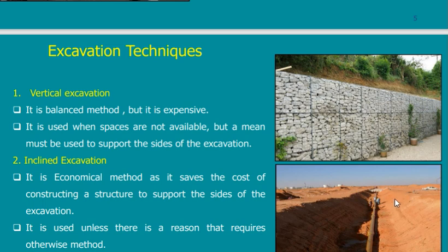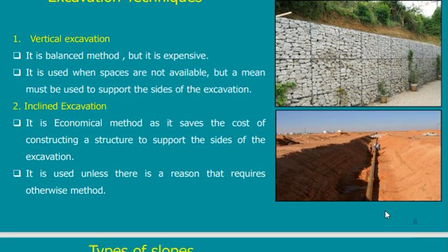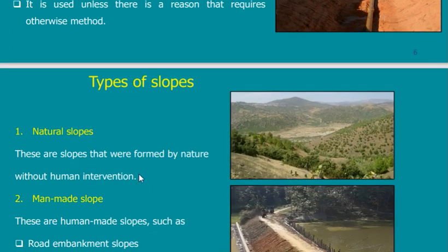In the case of this project in the desert, I don't care, because it's just a temporary period. I will just put my pipe and then backfill on top of it, and everything will return to normal. But if this slope is constructed to stay, then I have to check that it would not be affected by rainfall, earthquakes, or loads from any external forces on top of it. I have to check that it will stay as it is for its lifetime. So this is what I should do.